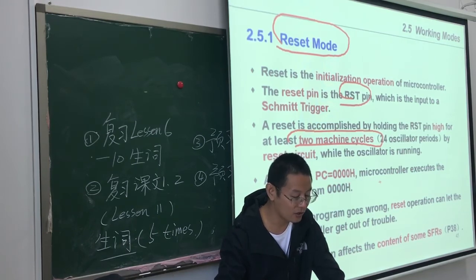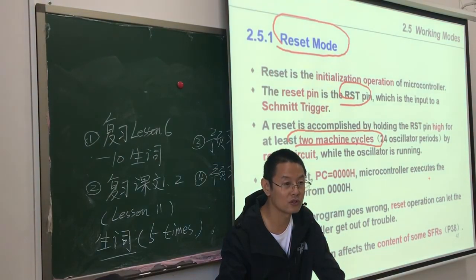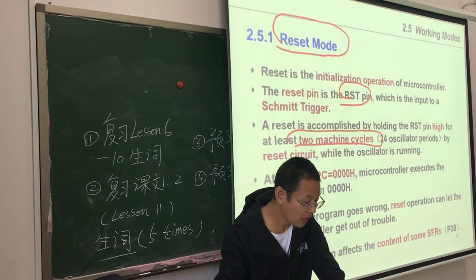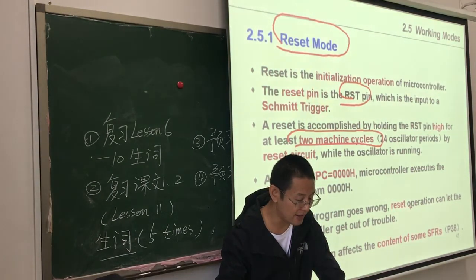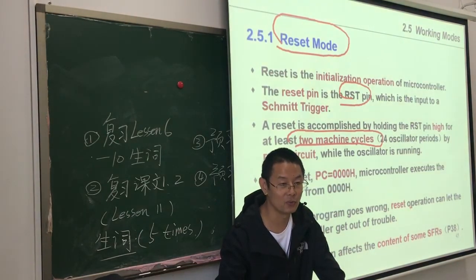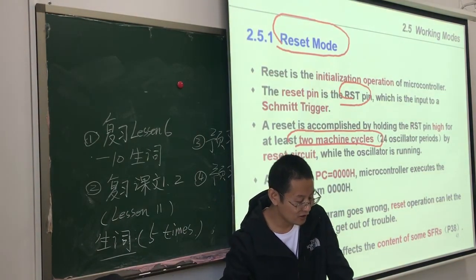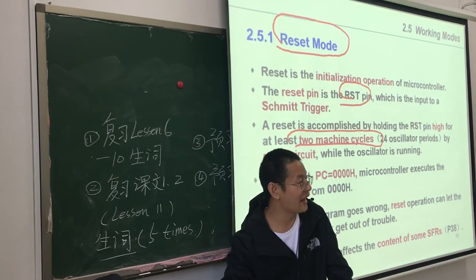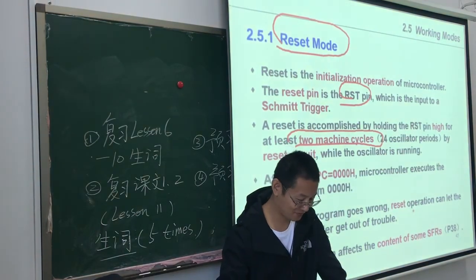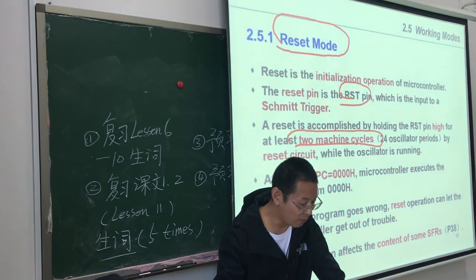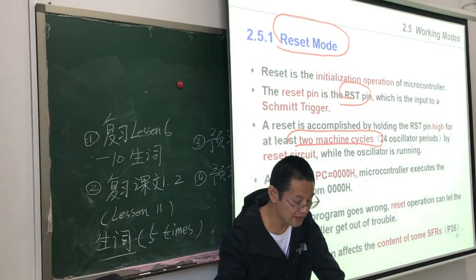The microcontroller then executes the program from 0H. When the program goes wrong, a reset operation can let the microcontroller get out of trouble. Reset operation affects the content of some SFRs.